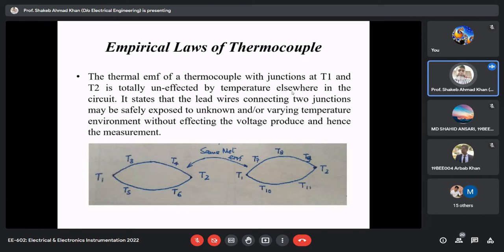And this lead resistance varies also. It's not like the lead resistance is constant. You can measure the lead resistance and then make the correction for that, but when the temperature and environmental conditions change, mainly temperature, then the lead resistance changes also. So the error is not constant, the error is dynamic.